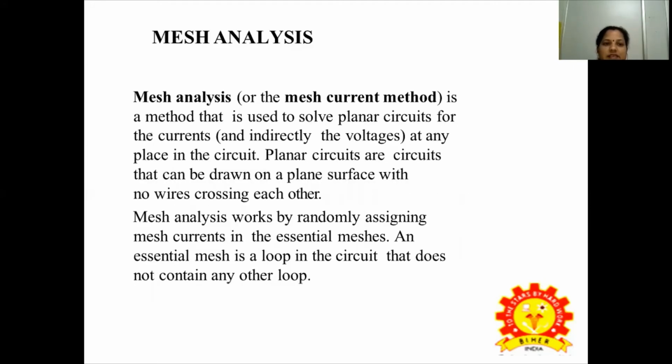So mesh analysis is a method used to solve planar circuits for the current at any place in the circuit. A planar circuit is a circuit that can be drawn on a plane surface with no wires crossing each other. Mesh analysis works by randomly assigning mesh currents in the essential meshes. An essential mesh is a loop in the circuit that does not contain any other loop.